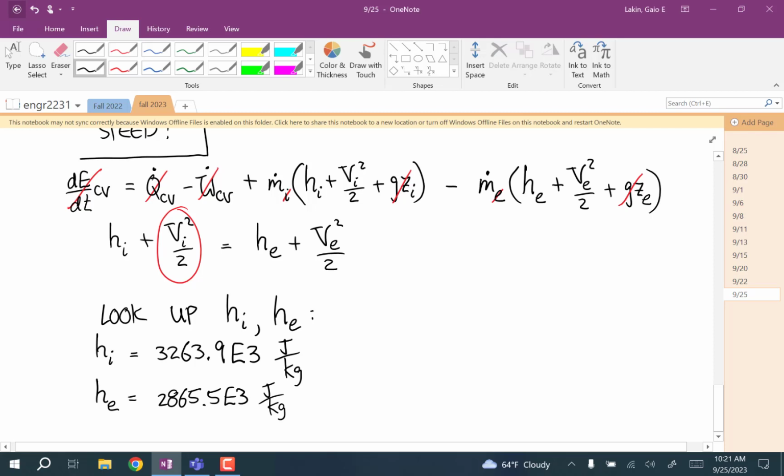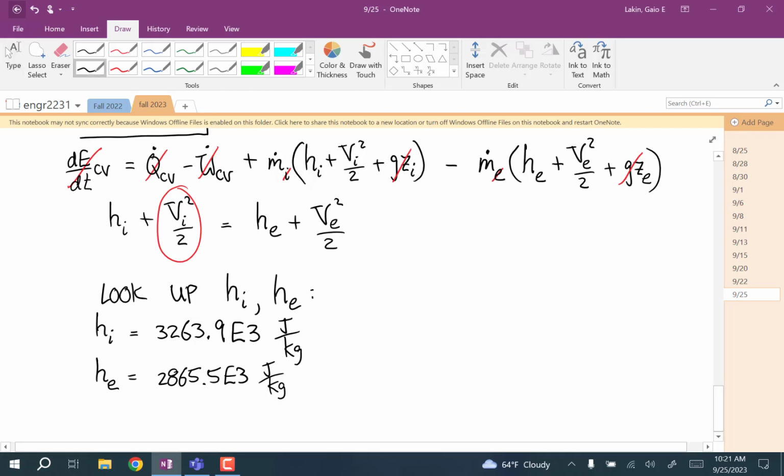Okay, one thing about units with the control volume equation. Up until now, I've always been using SI units pretty much. But you can use a lot of different types of units for the different things. But for this control volume first law, I think you probably always want to do it in SI units because your speed is going to be in meters per second. And if you're using kilojoules and then you're using SI units for the speeds or for the potential energies, everything's out of whack.